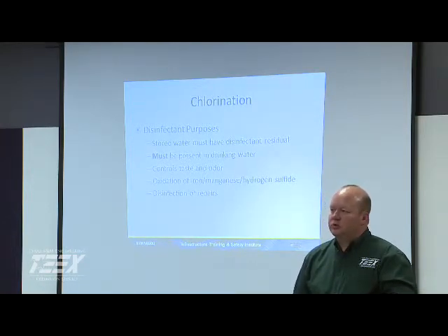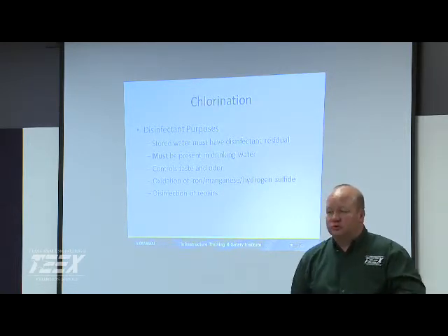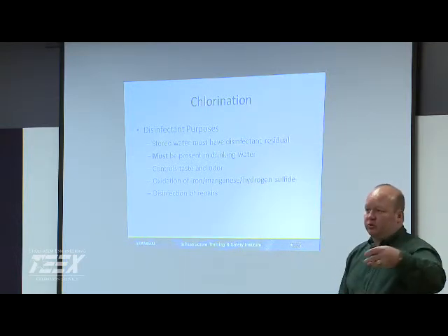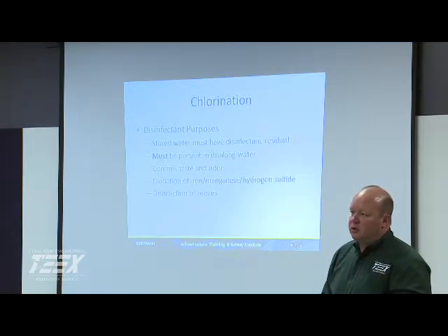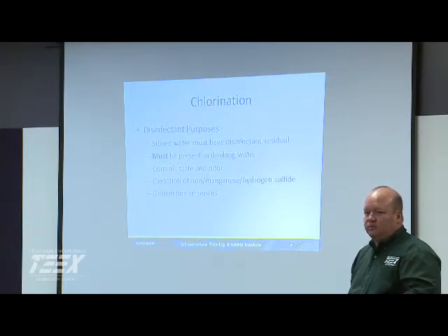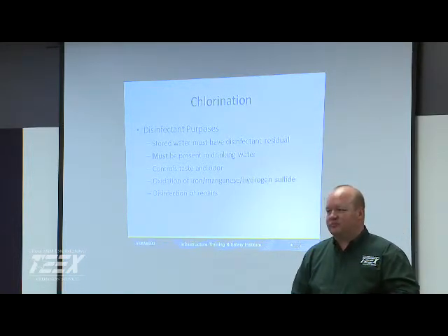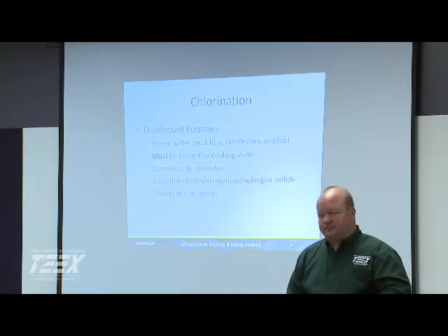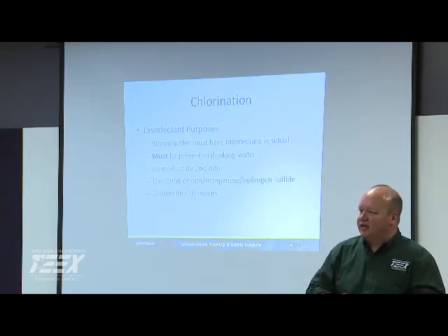But if you don't maintain positive system pressure, then we want to see a slug method of it. Okay, interesting. So if you're gonna do a slug, where are you doing your introduction? That's one of the reasons a lot of systems try and do it. Sure. It maintains positive system pressure, because sometimes there's not a good place to put it in. You have to pull a meter or something like that and try and dump it in, or put it in at the repair side, and you're trying to figure out how to push it back and forth to get the slug to go. You don't want to send it highly concentrated. So yeah, that'd be a challenge for sure.